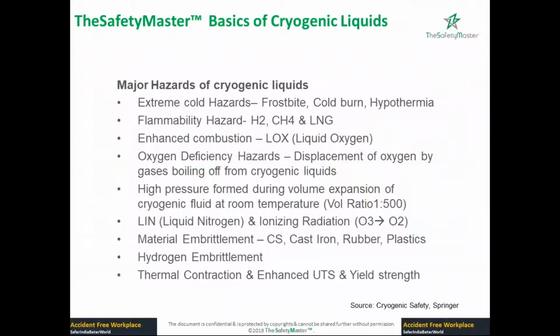Now let us look at the major hazards of cryogenic liquid. First, it is extremely cold. You can get frostbite if by mistake you touch a liquid nitrogen pipe which has not been insulated.